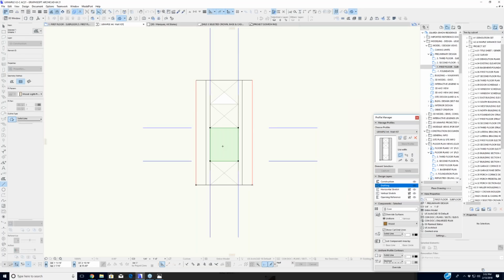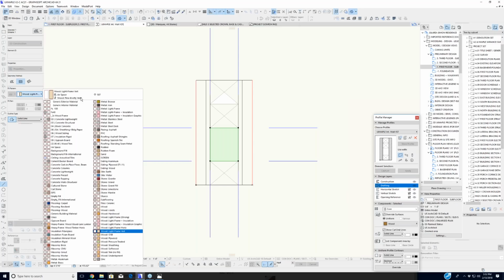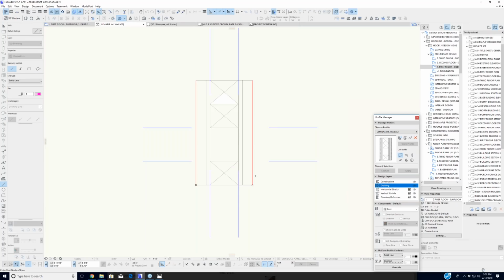material. And it also gets into, jump over here, it gets into the building priorities. So you have to also watch your building priorities. When I put a wood, let's say a wood floor here, I want the wood floor to either cut that or not cut that, or if this is sitting on a finished floor, I want the finished floor to be a smaller numbered priority than that.